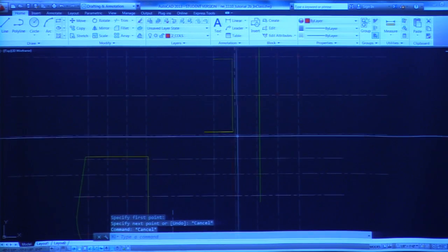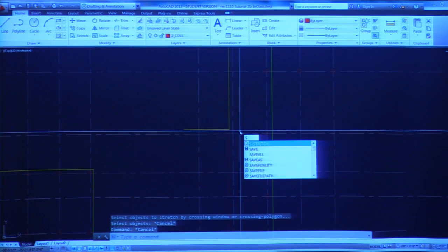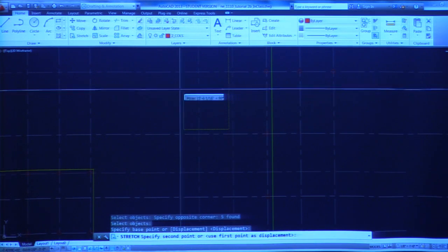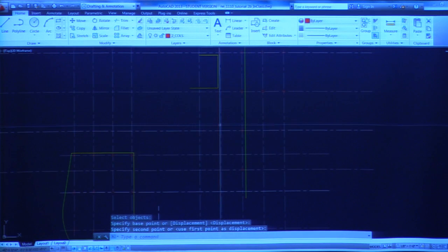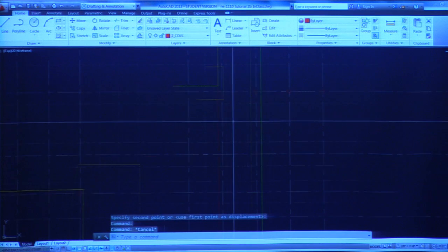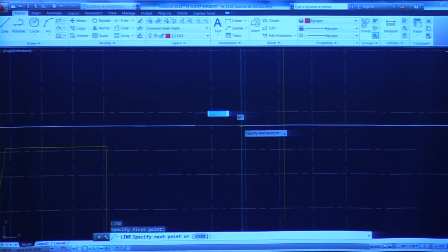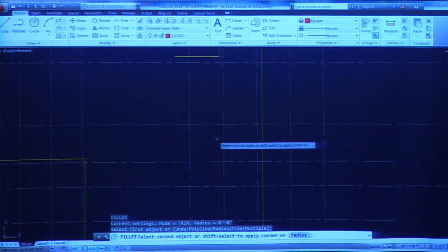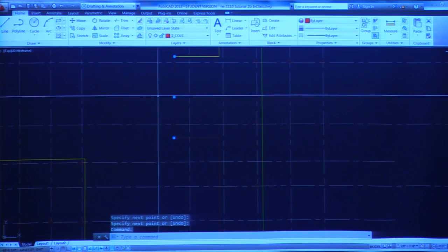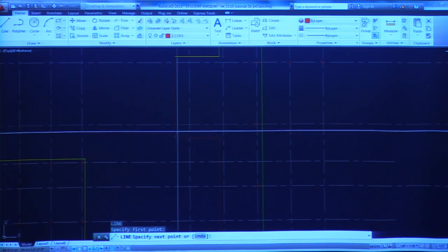If I stretch this, oh, here's another command, stretch. So I type S, space bar, and I do my little selection. And now I can stretch that element back this way if I want. Now I move not only this, but I move the endpoints of these all to one place there. I'm just doing this to make a little point about the section cut very quickly. Now I'm free-forming this shape. Oh, one more. There we go.